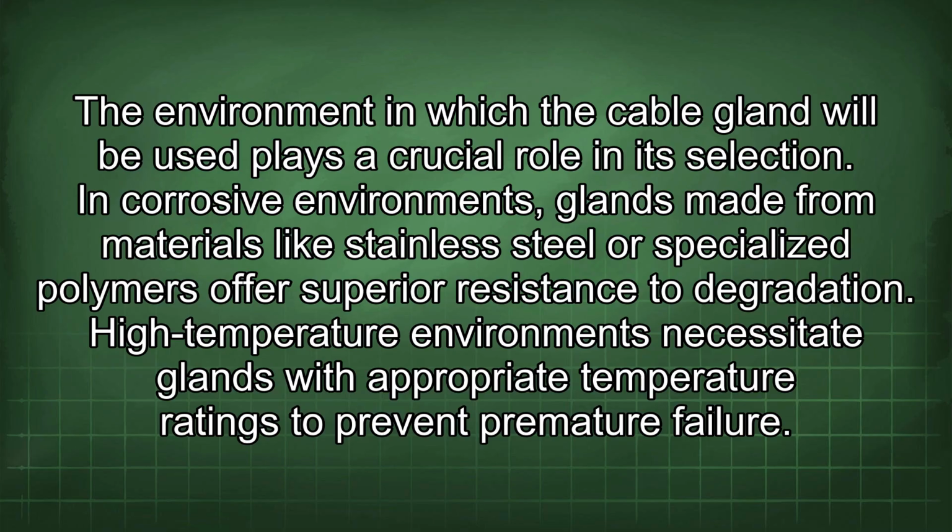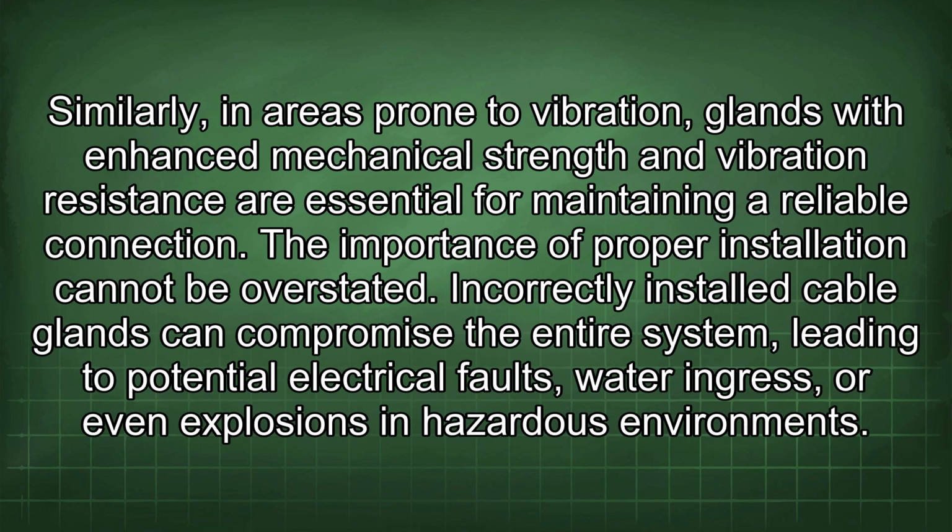The environment in which the cable gland will be used plays a crucial role in its selection. In corrosive environments, glands made from materials like stainless steel or specialized polymers offer superior resistance to degradation. High-temperature environments necessitate glands with appropriate temperature ratings to prevent premature failure. Similarly, in areas prone to vibration, glands with enhanced mechanical strength and vibration resistance are essential for maintaining a reliable connection. The importance of proper installation cannot be overstated.